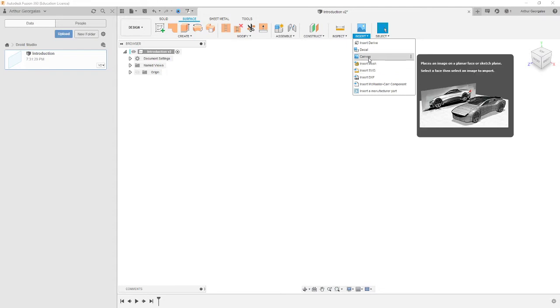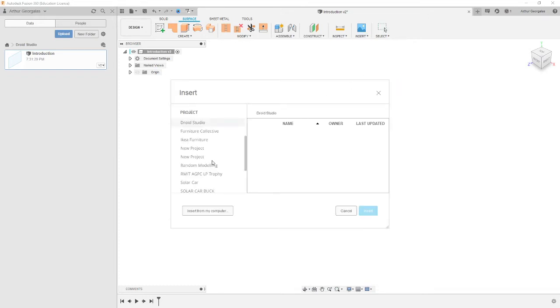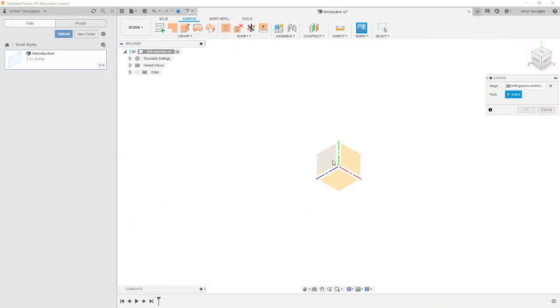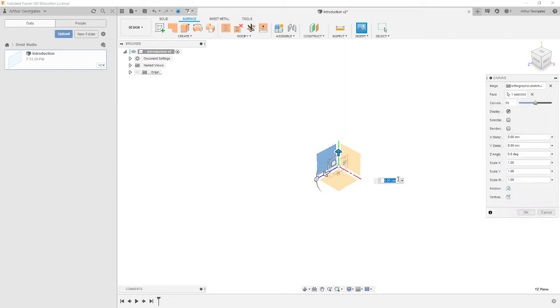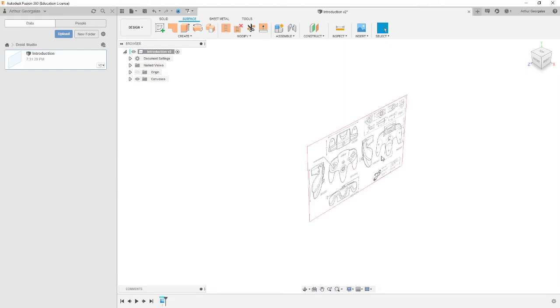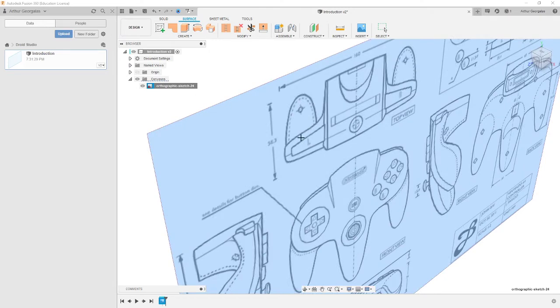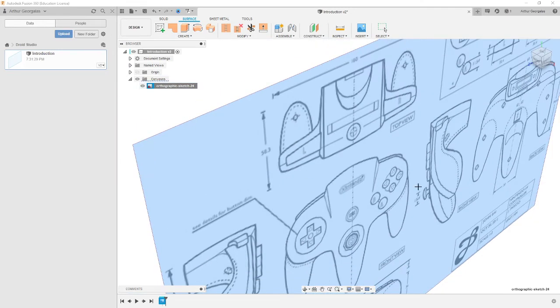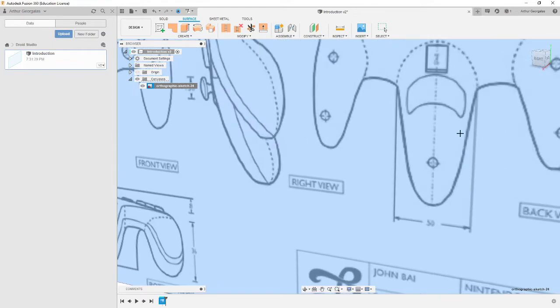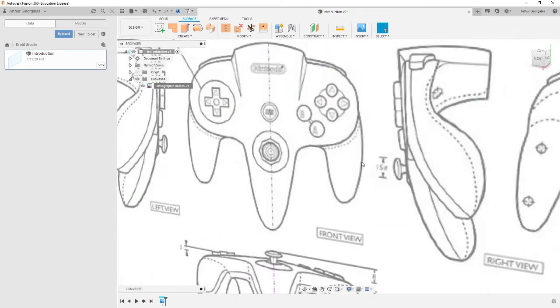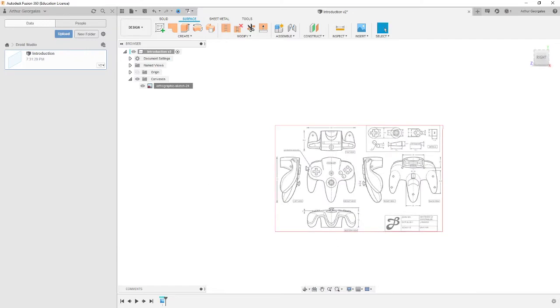So inserting a canvas is when we draw a sketch, we scan it, and we want to insert it. So, just for example, if I go to whatever's on my desktop from some stuff I've been looking at in Advanced CAD with my students, you can select it, put it there, come over to your canvas, right click, calibrate, and we can actually set some sizes based on this. This says from here to here is 50, so what we can do is click from here to here and punch in 50, assuming that's millimeters, and now this is scaled at the right size.